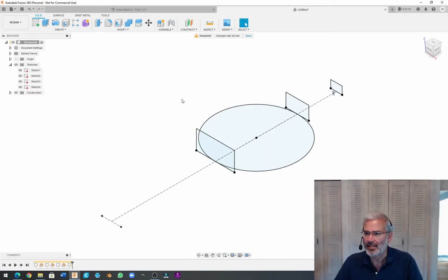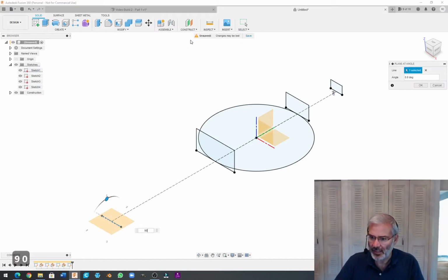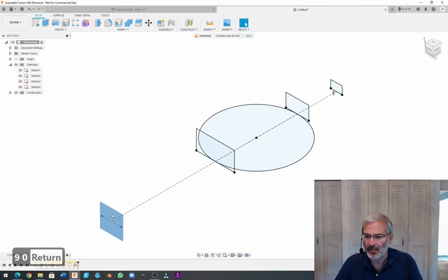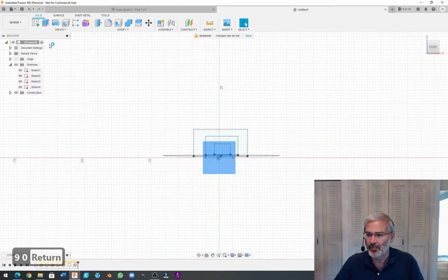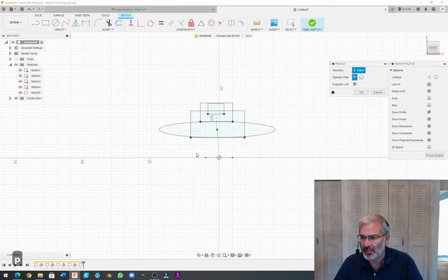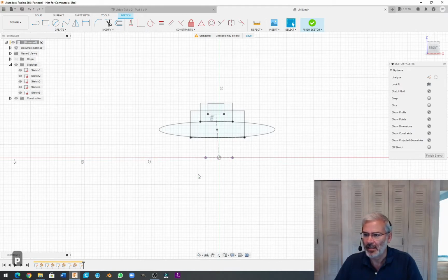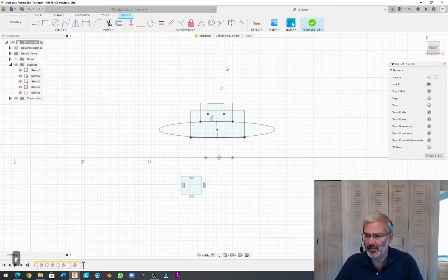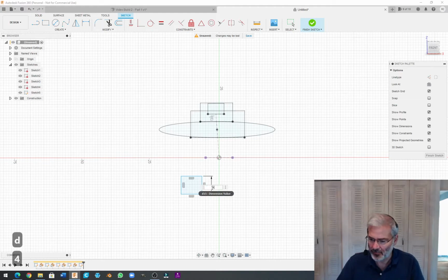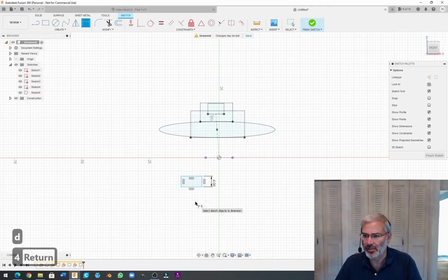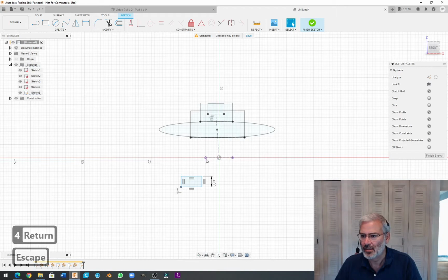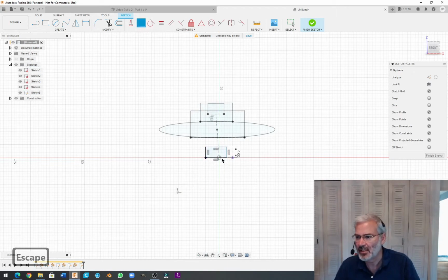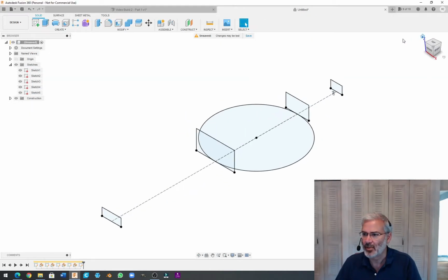And let's do the last one. So we'll click the last one, construct plane at an angle, 90 degrees. We'll select the plane. We'll create the sketch. We'll scooch down a little bit. We'll project onto those two dots and then use the rectangle key. And we will set the height of this one to 4 millimeters. So we'll dimension this to 4. And then we'll constrain this dot and this dot using the coincident, and again using those two. Let's take a look at our model.